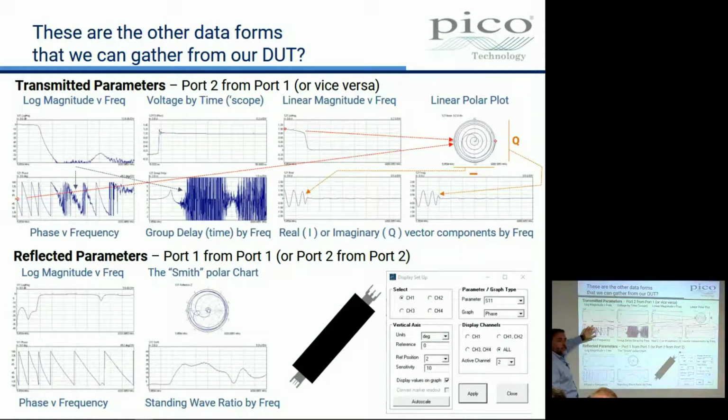Why does it go all noisy? Why am I not getting any sensible measurement here? Low amplitude. Look, I'm down in the noise floor here. So what I'm capturing is noisy signal, and I'm finding it hard to distinguish what the phase is of two noisy or one noisy signal. One of them's very low. The input's very high, but the output's very low. So this is correct. I cannot get phase. You can see when it comes back up again, look, I get it again. So we should expect phase to be noisy if the signal amplitude is very low.